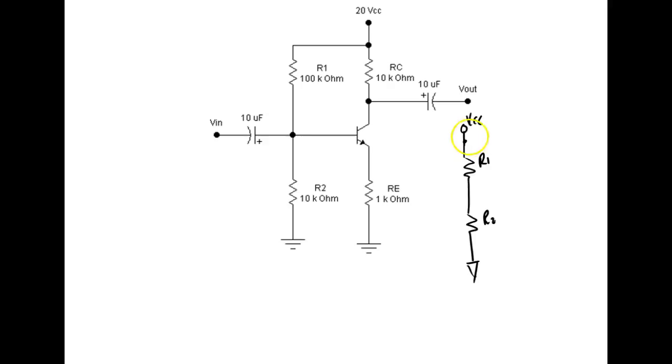You understand? And then what we do is we look at this circuit by itself, and we calculate this. And what we're going to do is I'm drawing the transistor as a rheostat. So this guy right here sets a voltage that we call VB, right? You understand? So when I calculate VB, I just calculate the voltage drop across R2. Then what do? Well, we come over here and we say the voltage drop across this resistor is equal to VB if it's silicon minus 0.7. That's what we do.